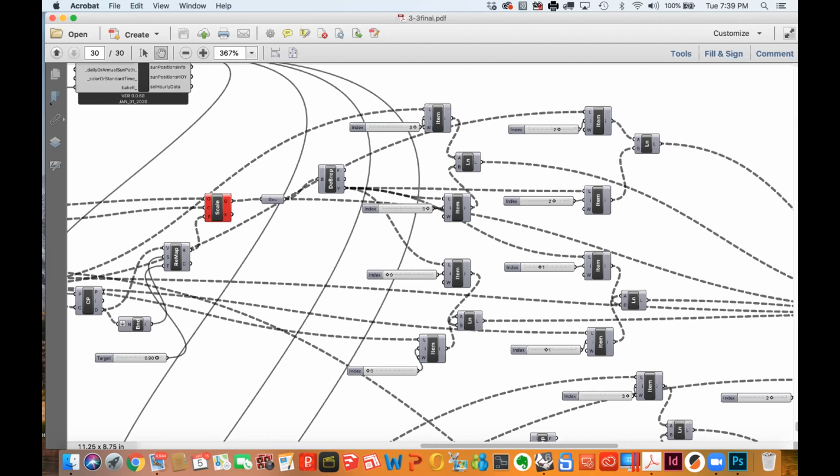The example that I love is the museum that Foster did in London. The one that's the kind of donut over the courtyard. It's the Royal, I forget the exact name of it, right? There's a round piece in the middle, and it's a triangular glass panel. Yes. The limitation of the glass sizes wasn't determined until fabrication, because the glass is fritted, which is a ceramic coating, and it was the size of the fritting ovens that determined how big the glass could be, right? There's no way you can know that until after it's bid. And if you do that in a traditional process, you have to redesign the entire project from the beginning if you get to that point and realize that your glass sizes were too big.